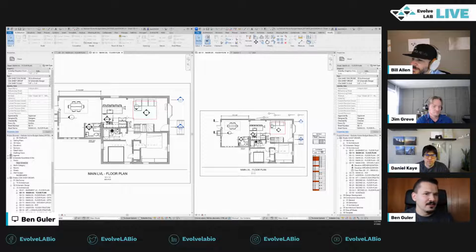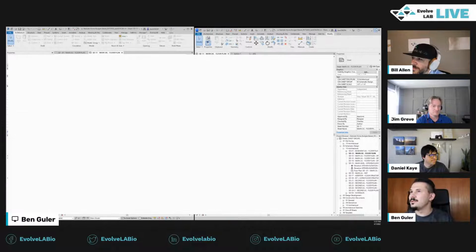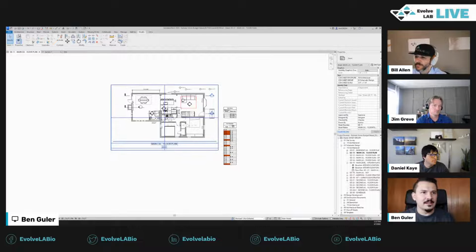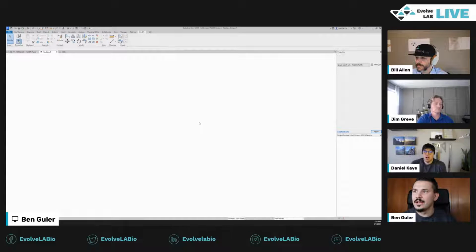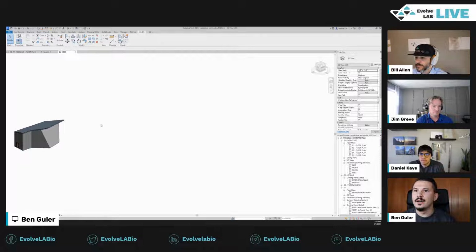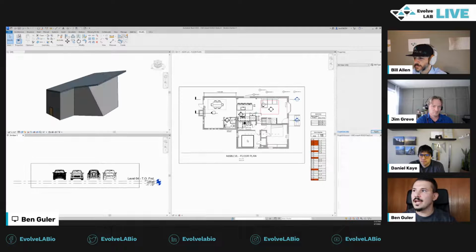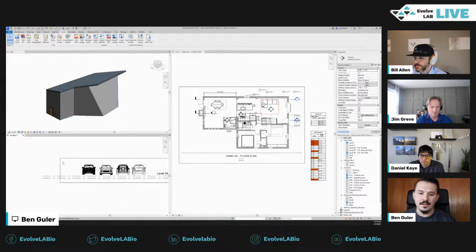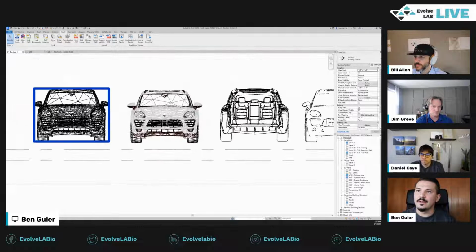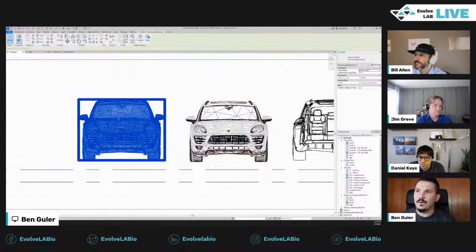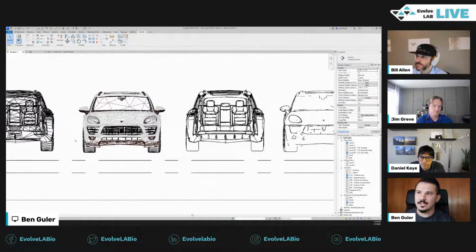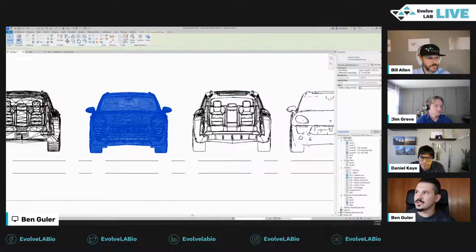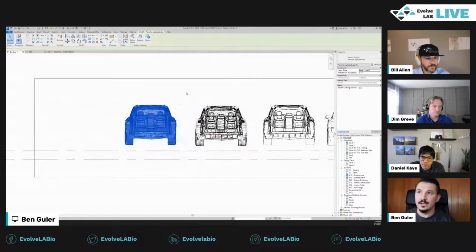Okay, so looking at cutting things, cuttable objects, I'll continue that. And they've also expanded that for imports. If you imported something into your 3D model, I just ran a test with importing a SketchUp model. So I just brought in an actual SketchUp import. And if I want to, I can turn this on, and this wasn't a feature before, where you can actually cut, this is a section cut essentially. You can turn that on and it section cuts those objects in a section drawing.